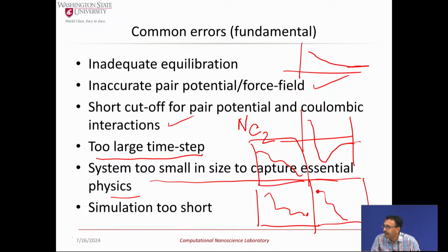I presume there are boundary conditions besides periodic boundary conditions that you can impose, right? Yes. So for example, the software LAMMPS has many other boundary conditions besides periodic. Number one, it can be periodic in certain directions and not in all directions. You can have a shrink-wrapped boundary condition where you're letting the atoms on that boundary go beyond, but you're still keeping it within the domain.